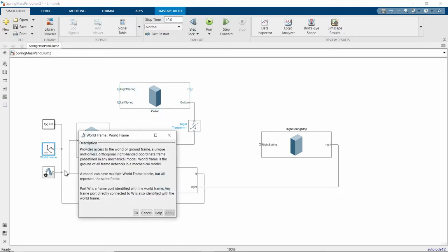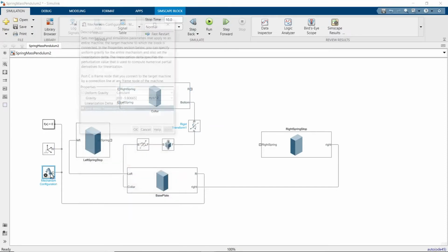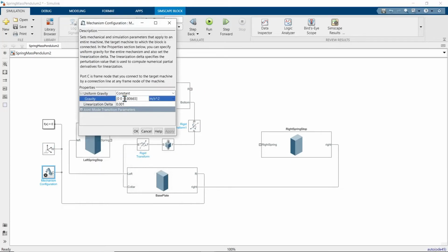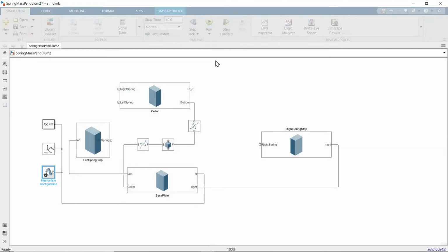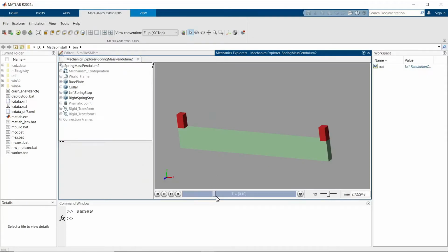So now, like we said, we're going to change gravity and put it in the x direction to see what happens. Change it to 0 in the z and positive 9.8 in the x. So we'll expect this color to slide forward. And it already slid forward so fast we didn't even have time to see it. So there it's sliding forward in the x direction.